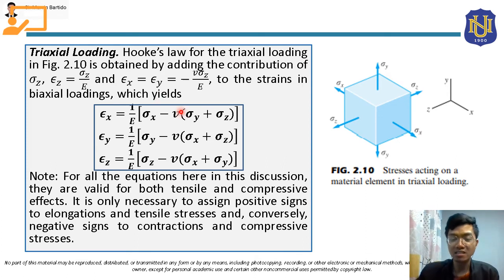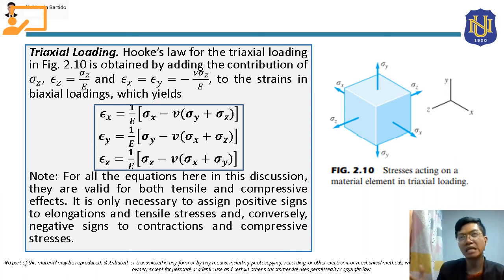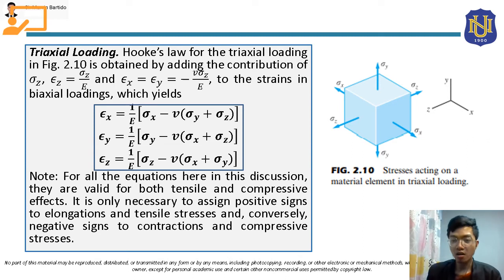But if the stress is in compression, we have to include the negative sign when we substitute the value of that stress in these formulas. Again, for tensile stresses it will be positive, and for compressive stresses it will be negative. So take note of that, class. In this case, all these stresses are tensile, so they are all positive.